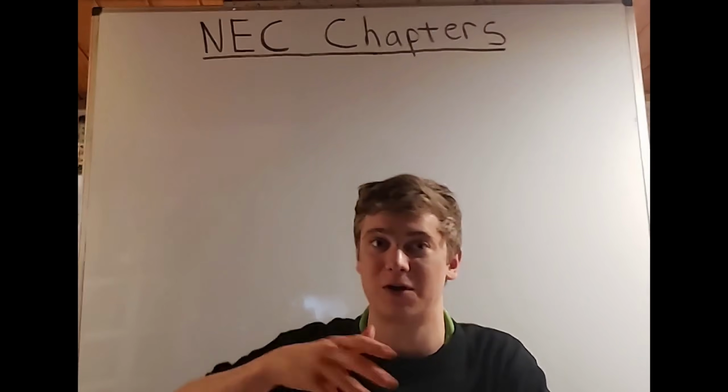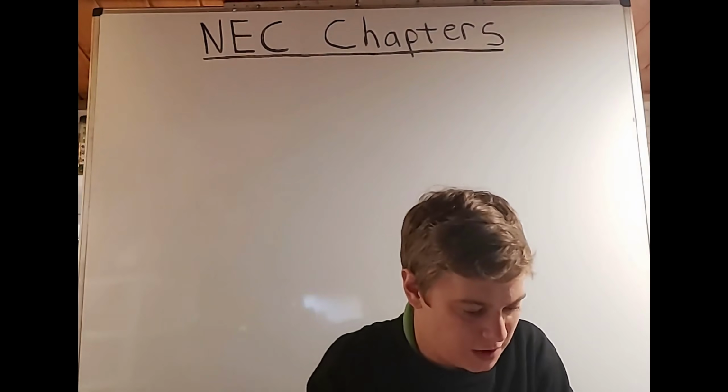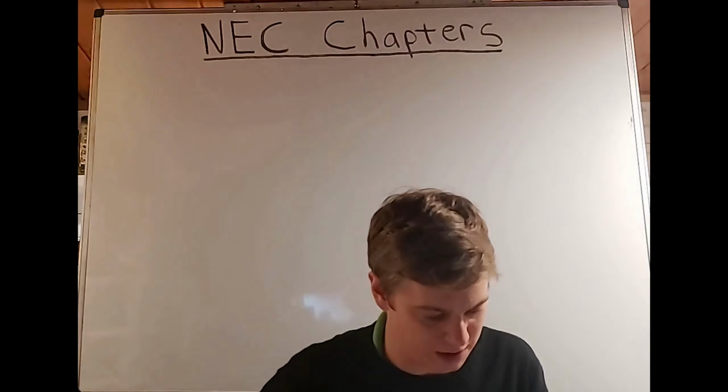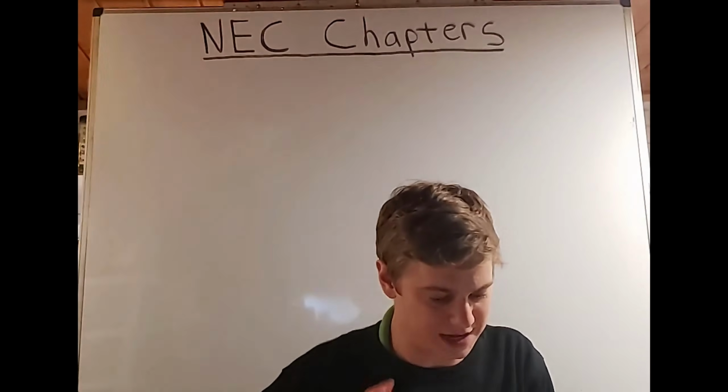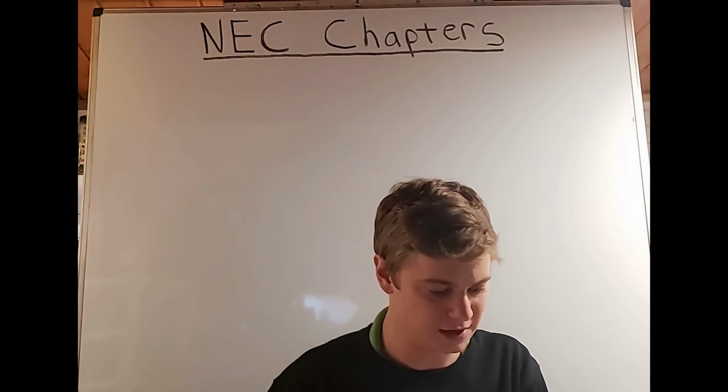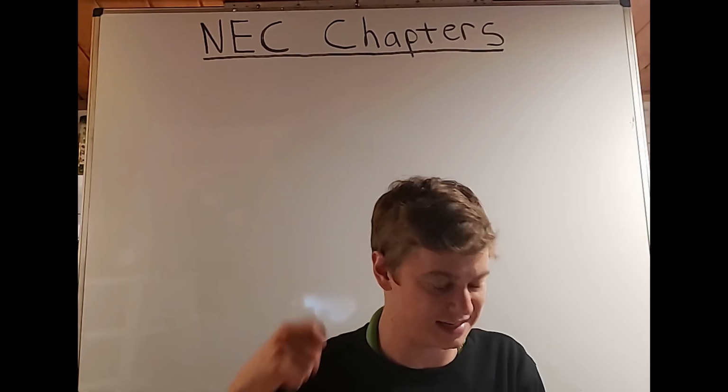Okay, I'm going to finish up Article 200 with 200.11, polarity of connections, where it just mentions that if you have grounded conductors, no grounded conductors shall be attached to any terminal or lead so that it reverses the designated polarity.